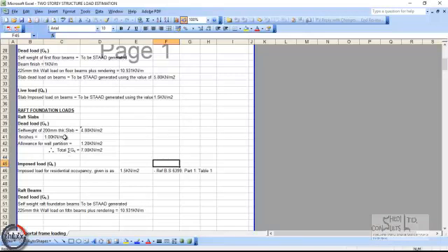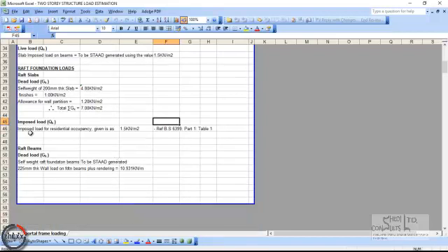So finishes we took as 1 kilonewton per meter square, and then additional loads for wall partition was taken as 1.2. The summation of these loads gives the total dead load as 7 kilonewton per meter square. The imposed load is taken as 1.5 kilonewton per meter square, to capture walkway requirements, obtained from the same code reference. The self weight of the raft beams is to be calculated automatically by STAAD so long as you model the raft beams correctly, and you specify its geometric properties and its corresponding density.